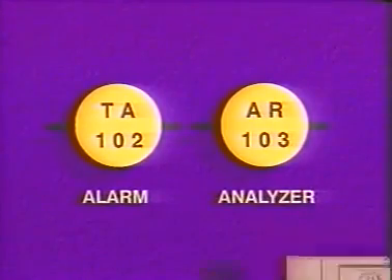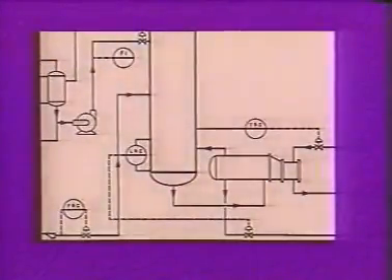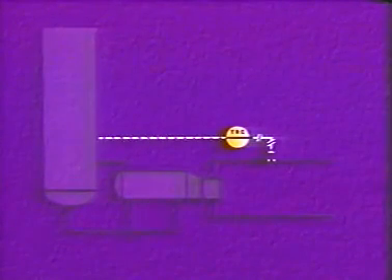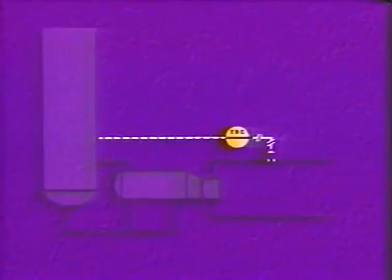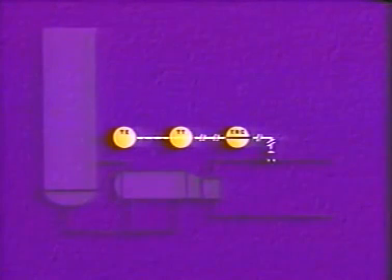Process piping and the walls of process vessels are usually shown as solid, unbroken lines. The lines supplying air to process instruments are shown by short diagonal marks crossing a solid line. Here, a valve is connected to a controller by an air line. Electrical signals and electricity supplied to instruments are indicated by dotted or dashed lines. These symbols show a thermocouple, the electrical wiring between the thermocouple and a transmitter, and a pneumatic air line from the transmitter to a controller.